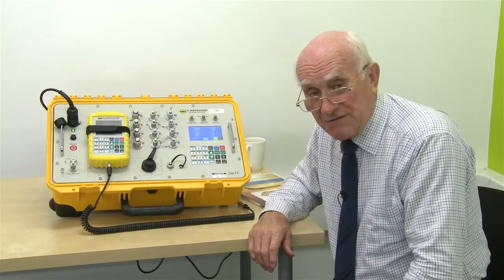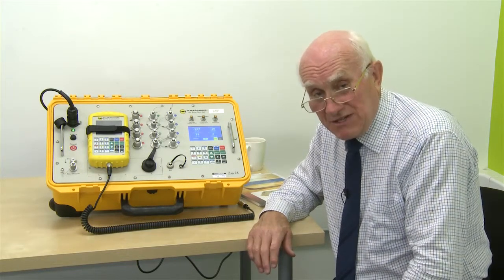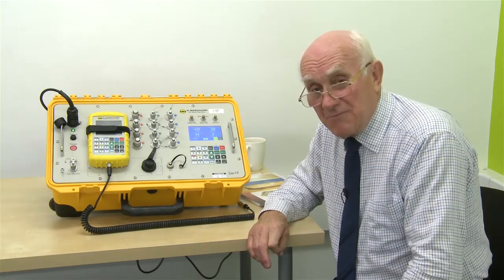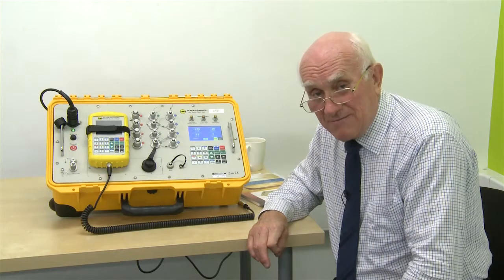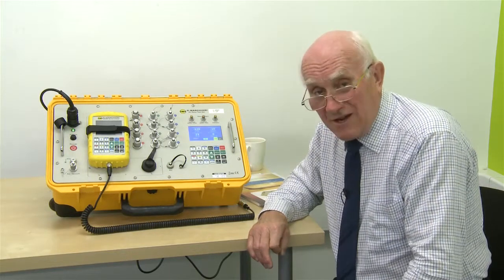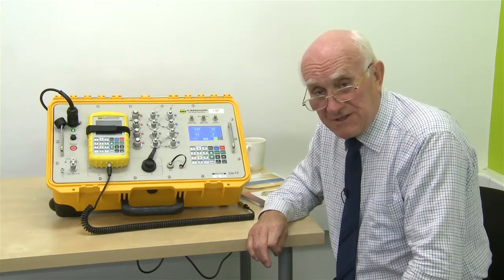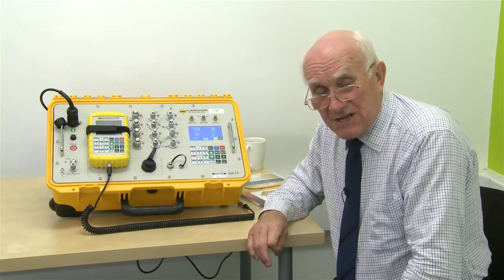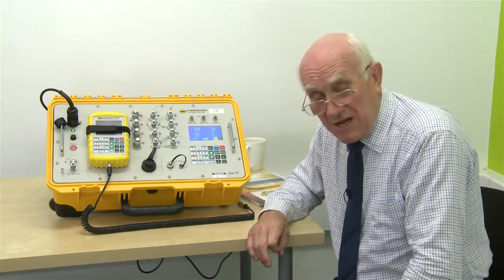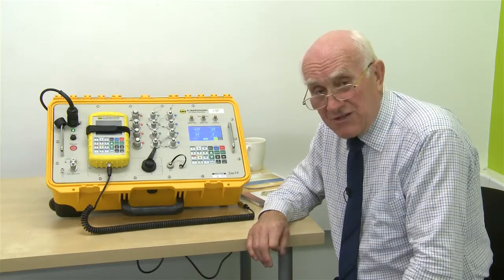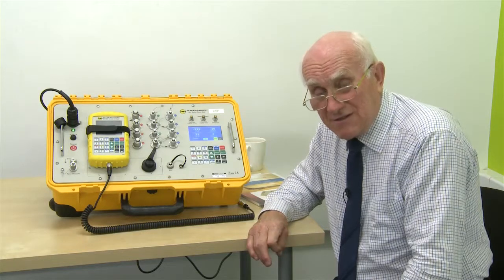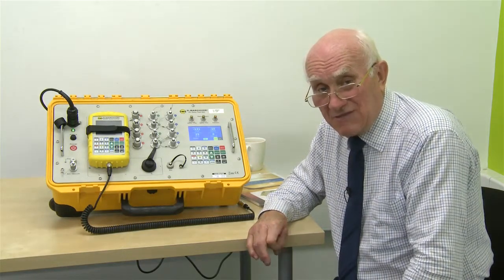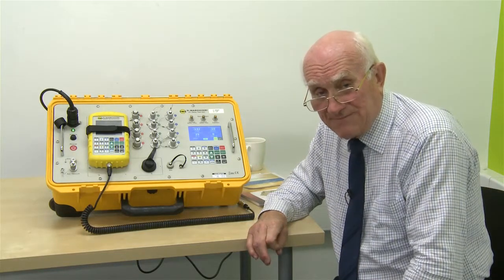is the MPS 45, is a twin channel instrument, a conventional pitot-static altitude and pitot-total for airspeed. The MPS 49, however, is a three-channel instrument. Not only does it do the conventional static and pitot, altitude and airspeed, but additionally a third channel for angle of attack, so that you can check out the more recent pneumatic angle of attack sensors on the aircraft.